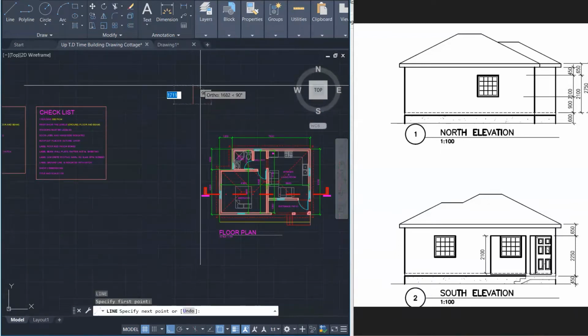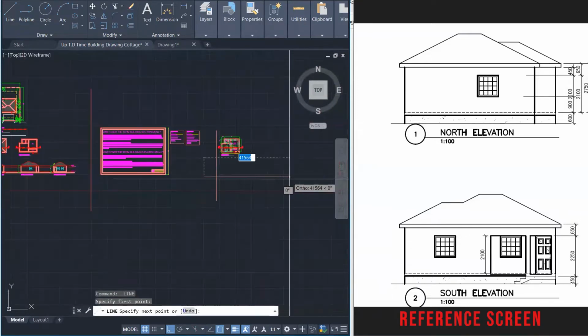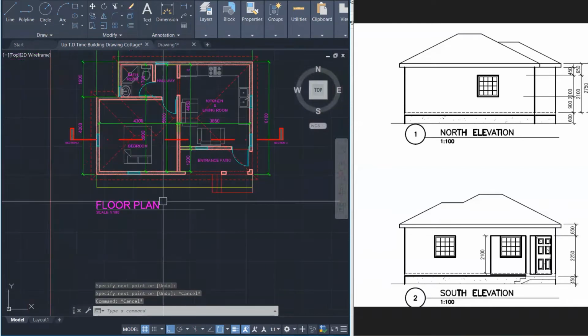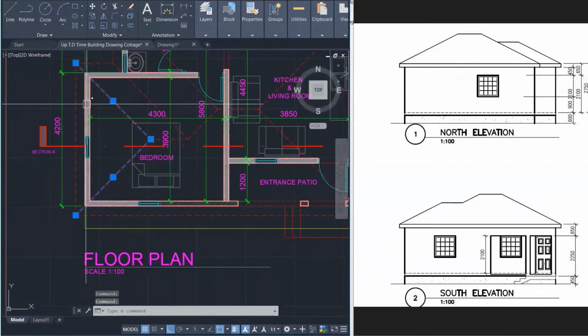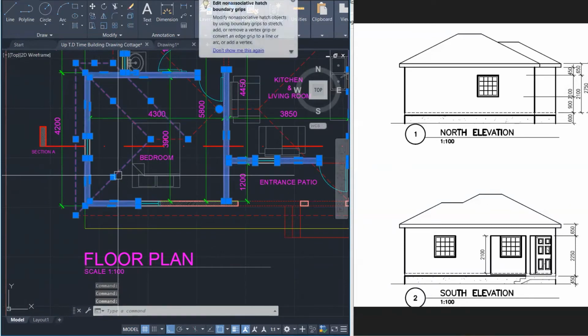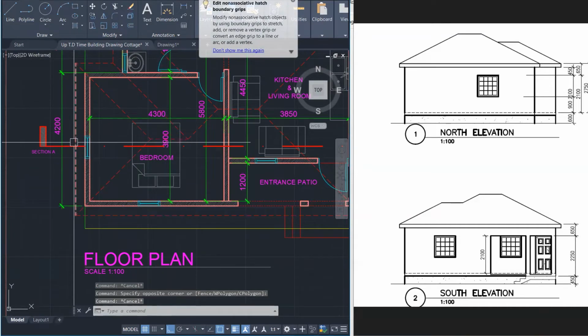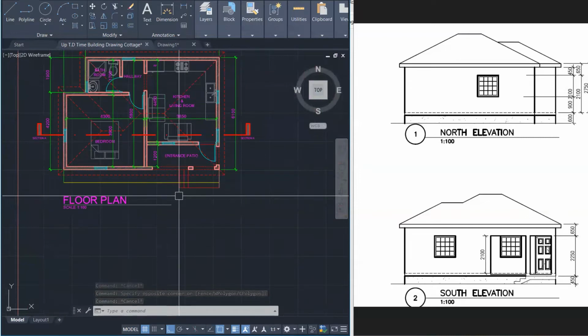I'm going to draw down a line to shut off that side of the screen. So I'm going to be working in this area here. Why did I bring this floor plan? Because this floor plan has the roof outline in a hidden line, and it also has the walls. So it has all the information I need, and it has the location of the windows. So first I need to identify, am I looking at my south elevation? Yes, these two correspond.